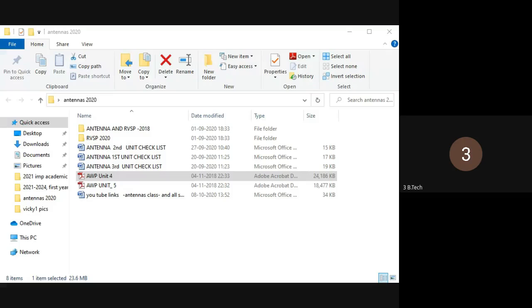So n lambda by 2 long wave antenna condition. Long wave antenna examples are the V antenna, inverted V antenna, and rhombic antenna. These antennas are used specially when it is desired to operate on a number of frequencies. Due to changing ionospheric conditions, even in critical climatic conditions, these antennas operate.